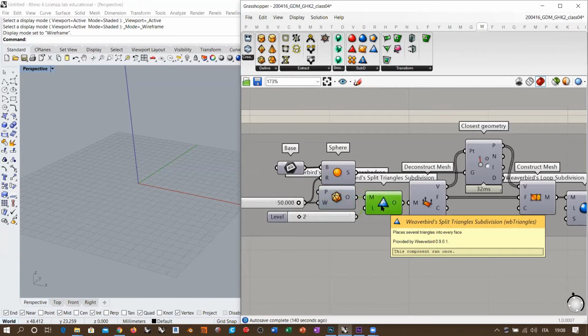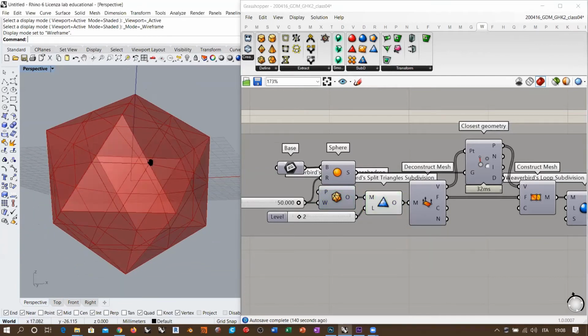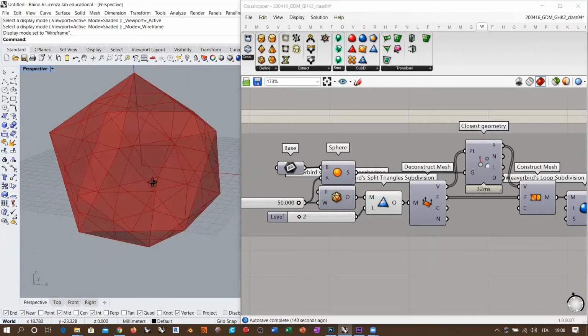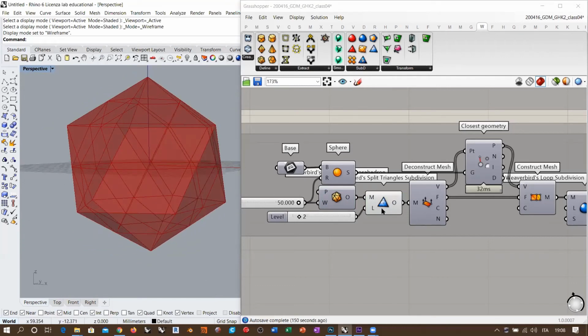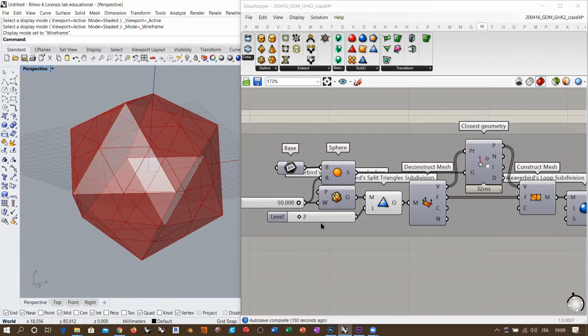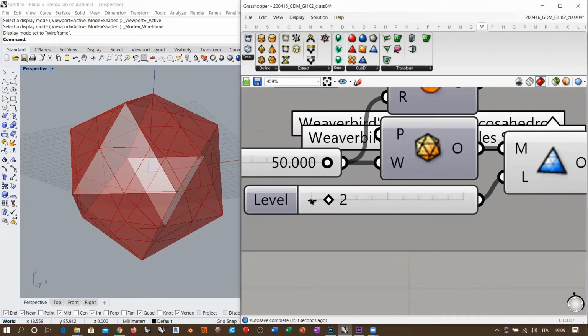And this is actually creating a higher resolution for this mesh, always based on triangles. Okay. So you see that this is based on how many iterations you want for your subdivision. If you say I want just one iteration, it means that each edge is divided only by one. So you get the same mesh as a result.